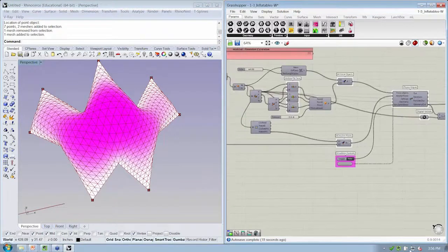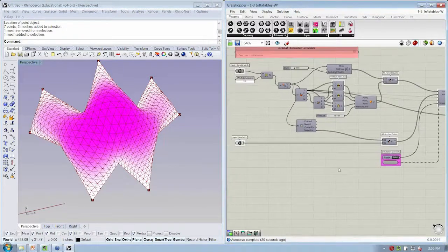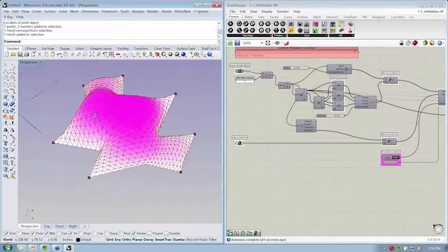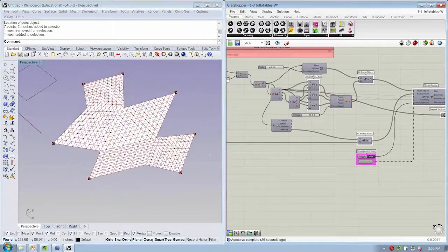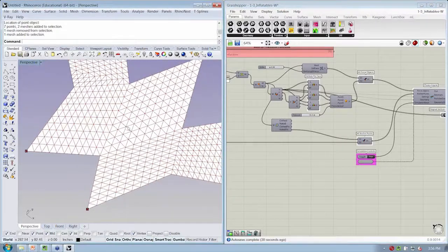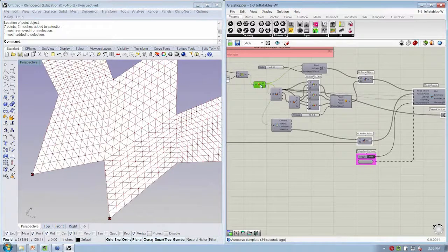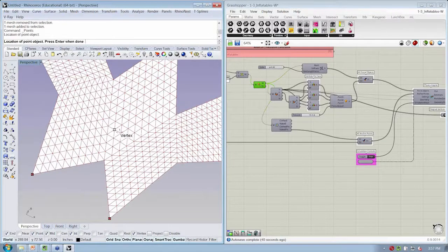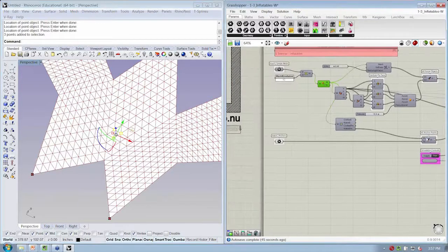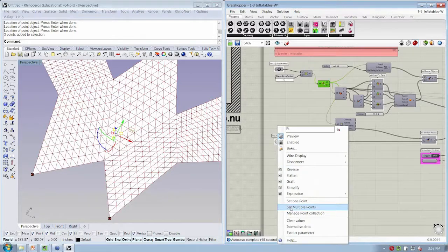And then one more thing I wanted to show is that you can hybridize an automatic edge condition and something internal to the original mesh. So let's say I wanted to create a column within my inflatable around here. Well, I can take this mesh and bake it real quick so that I have the vertices to snap to, add a couple of points in here, and then because I've got this merge working, I've got the naked points and I can supply my own input anchors.